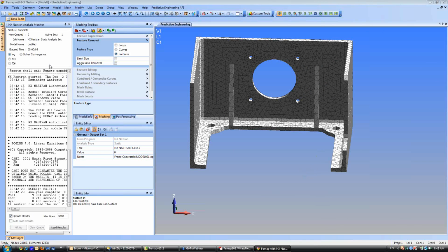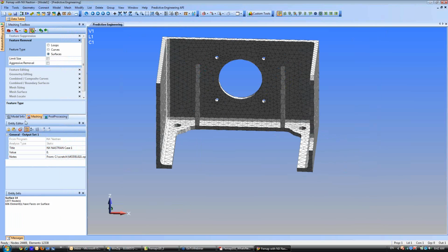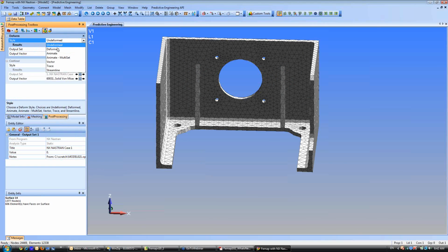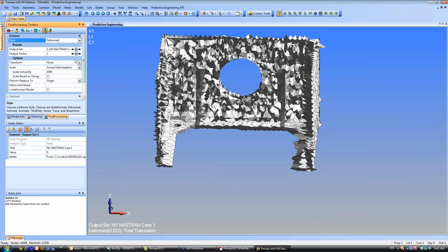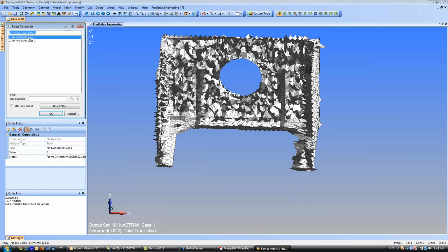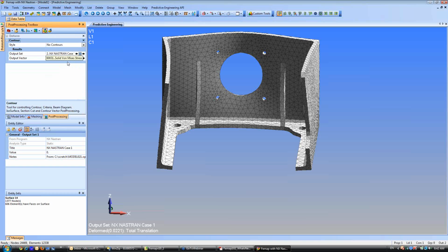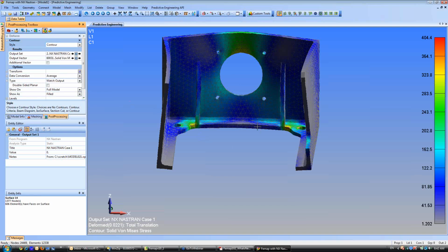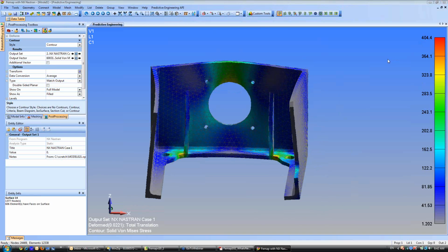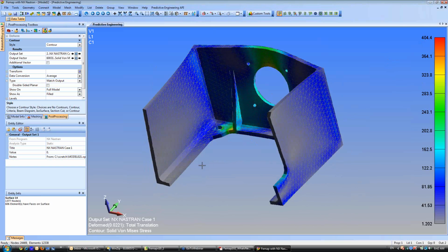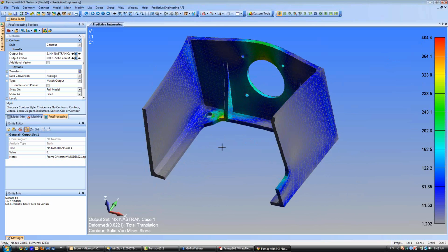Okay. It just always gets me how fast it is. I actually ran it, first way I did this presentation, I ran it with a regular solver. It took 30 seconds. It takes like 5. Deformed. You guys have already seen this. Why? Because we have 2 load sets in there. A contour, second, no contour. We want to contour like that. And actually, the stress went down a bit, getting rid of the ribs, because it allowed a little bit more flexibility here on the side.